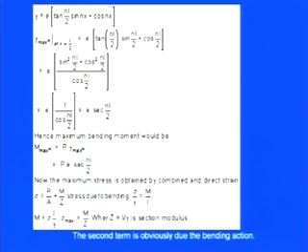So by keeping this M by Z, we have the combined stress. We have a real feeling that whenever a strut is under the action of axial forces, the buckling load can be easily calculated using two main components. If we are talking about the stress, then we have two main components: one is due to the bending moment, M by Z, and one is due to the applied load, P by A. That's why we have a clear feeling that the second term is coming because of the bending action, which we were ignoring in the basic form of the Euler theory.